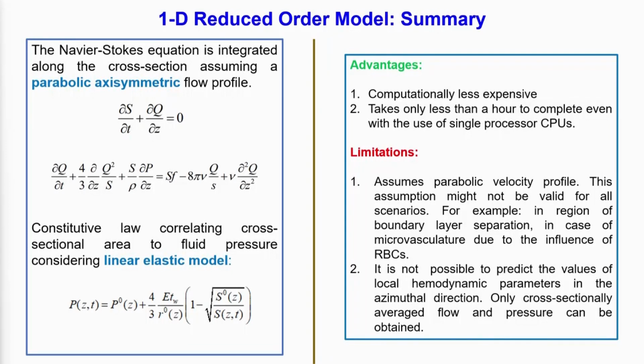So, the summary is that now you have two equations, one is the area averaged continuity equation number 1, and number 2 is the area average momentum equation, which we have just seen how it is derived. So, we have assumed a parabolic axisymmetric profile. If you have anything different, you will have the algebra different, but method the same.